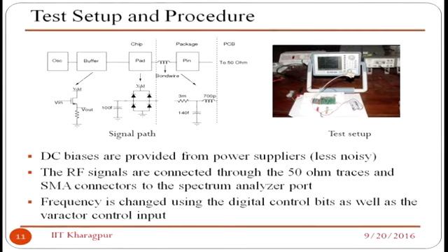To isolate the external capacitance from the internal one, use some kind of buffer. That buffer is simply a source follower. Remember, when you do the layout, don't forget to make those buffers. Whenever there is an external pin, you should have a buffer to avoid this impedance mismatch or the parasitic capacitance.